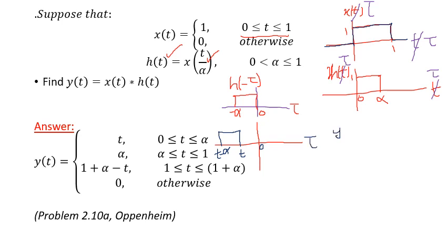Okay, I can write y of t equals 0, right? And this remains 0 until, because you keep shifting the signal towards this side, t equals 0. At that point the response is non-zero, which is this one, and the input signal is non-zero, which is this one. So that means we have non-zero overlap. So y of t equals 0 when t is less than 0.